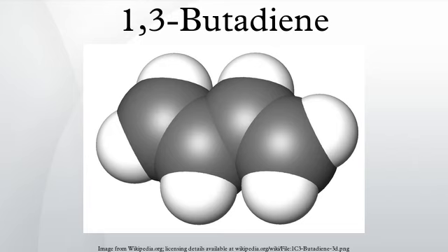and aromatic hydrocarbons. Butadiene is typically isolated from the other four-carbon hydrocarbons produced in steam cracking by extractive distillation using a polar aprotic solvent such as acetonitrile, N-methylpyrrolidone, furfural, or dimethylformamide, from which it is then stripped by distillation. From dehydrogenation of n-butane.